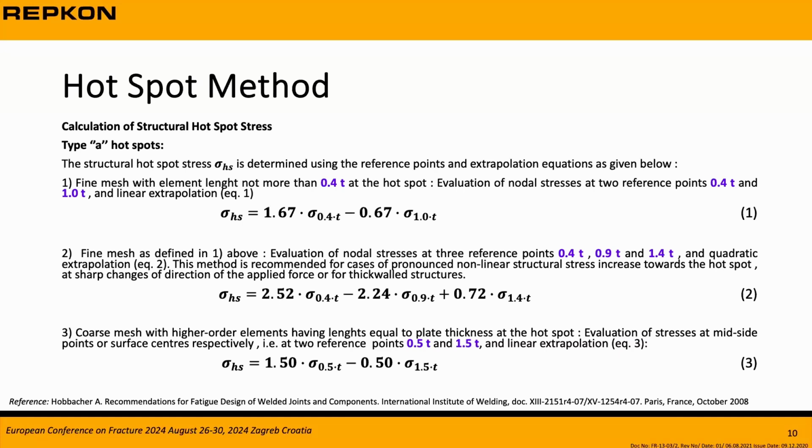Coarse mesh with higher order element having lengths equal to plate thickness at the hotspot. Evaluation of stresses at mid-side point or surface centers respectively, two reference points, 0.5 T and 1.5 T, and linear extrapolation equations are given here.